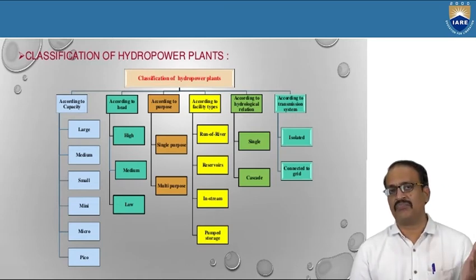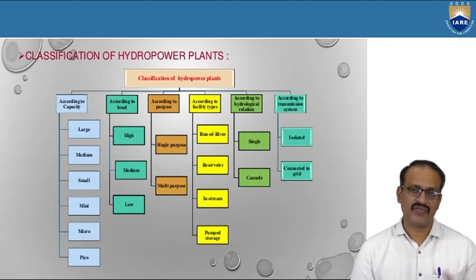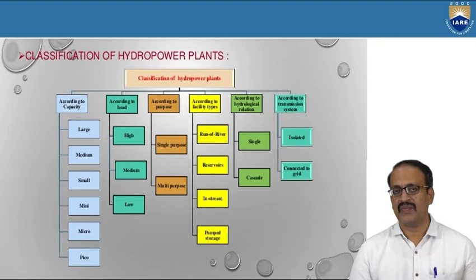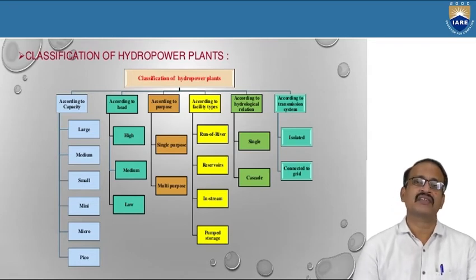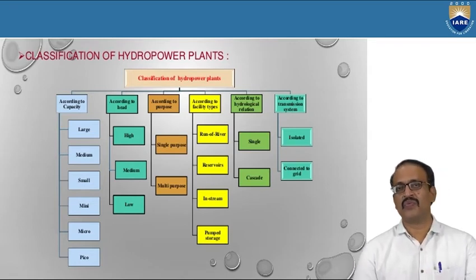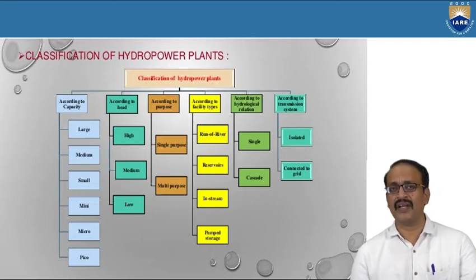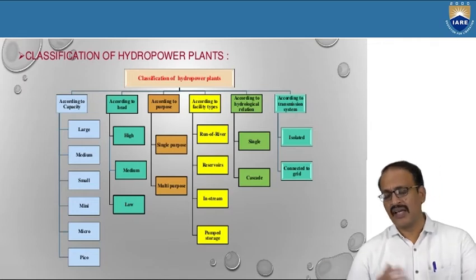We can consider both the Nagarjuna Sagar Dam and Srisailam Dam as large dams. But Nagarjuna Sagar Dam is larger than the Srisailam Dam, yet because of the higher head, the Srisailam Dam is able to produce more power than the Nagarjuna Sagar Dam, even though it is less large.